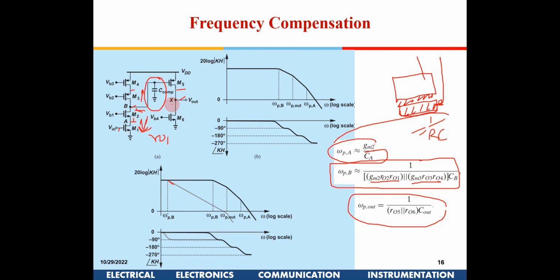If it is an open loop, there is no issue, but in analog, we saw that generally we use it in a feedback path, right? So, in those cases, to avoid oscillations, we put these kinds of capacitances in between to make it stable. Is it okay with all of you till here?